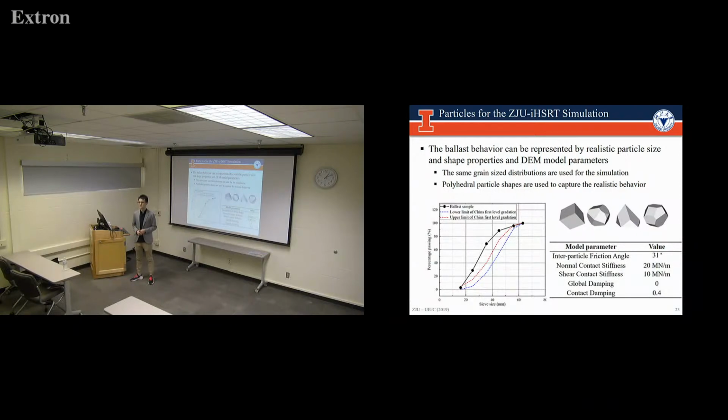Because when you think about the life cycle of the ballast, it's the most drastic change you can imagine. The layer completely changes from being large rocks to a well-graded gradation. Really huge, drastic change as it becomes older used ballast, right?